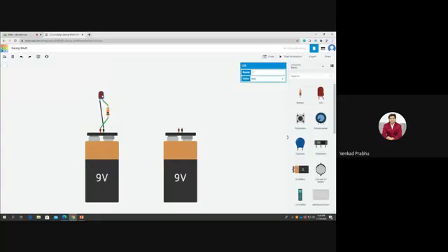That's it. If you want, you can change the color of the wires, you can change it to red color. So now this is the circuit as per the circuit design which I saw before in the TinkerCAD PPT. So just click the start simulation. Now you can see that the LED is on without any alert message. So this is the basic circuit, positive to resistor, and then to the LED positive, and negative directly to the cathode.